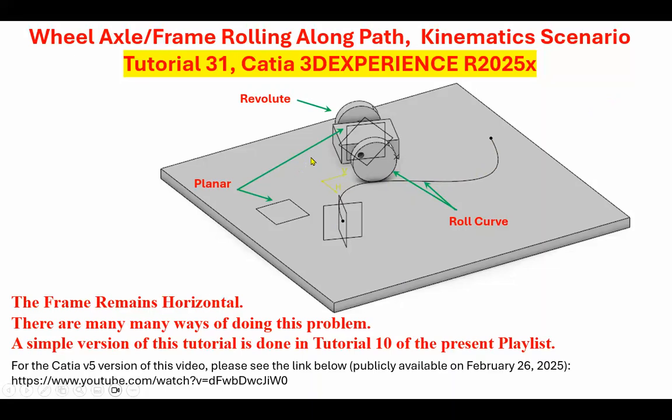And in order to make sure that this frame stays horizontal, one way of doing it is to create a planar joint between the top of this frame and a plane that we create later on and is at the same height as the top of that plane. Okay, so we will see that in a minute.